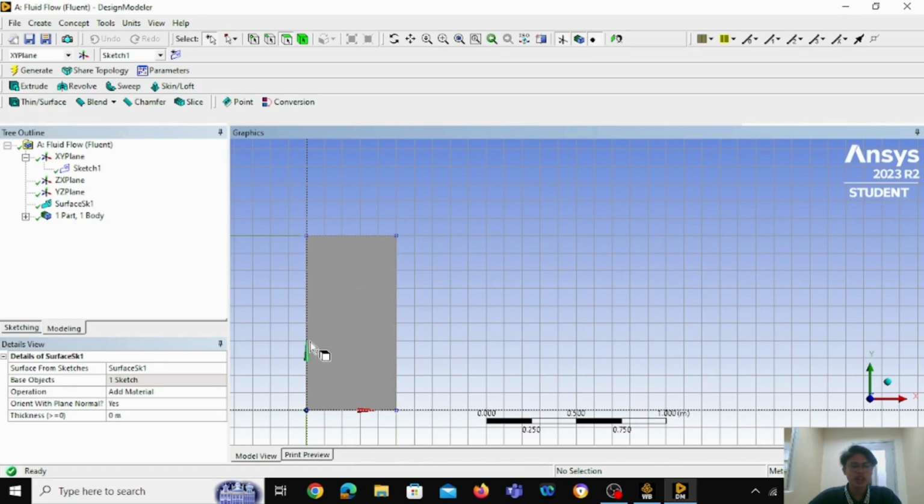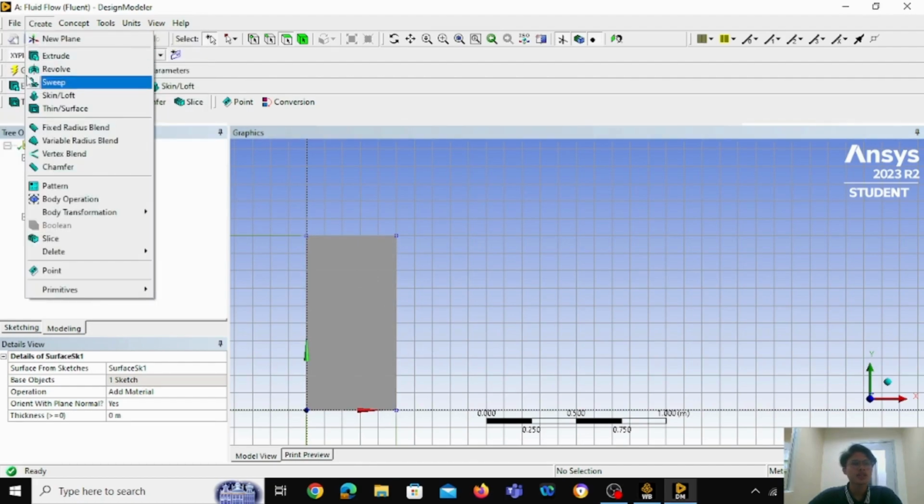The left boundary is where the flow is entering. So this is the inlet, and the right side is our outlet. So the flow will eventually leave. We can just assume a constant pressure boundary at the end. So I will finish our geometry. And I would like to save the project.